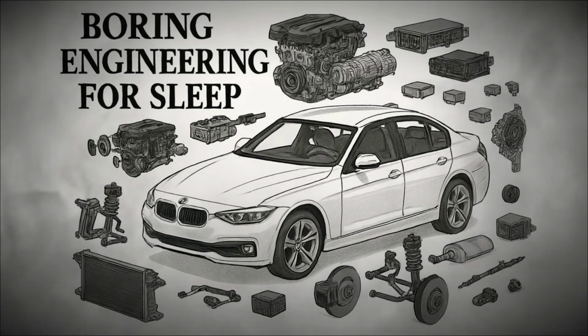Without a muffler, the sound of an engine would be unbearably loud, since each cylinder firing creates a sharp pulse of high-pressure gas. The muffler allows a car to operate at a noise level acceptable for everyday use, while still allowing free flow of gases. Some systems also include a resonator, which fine-tunes the exhaust sound and can reduce certain frequencies of noise.